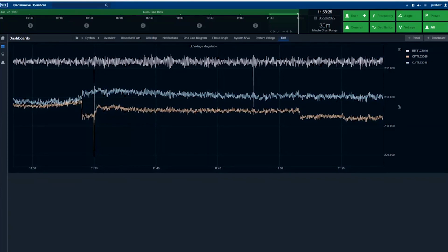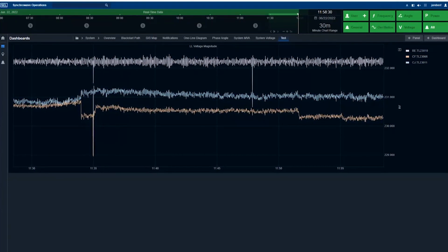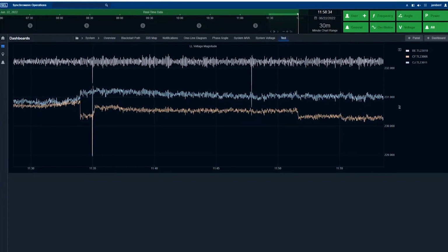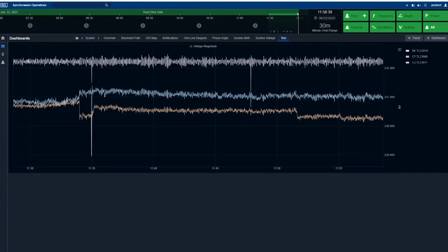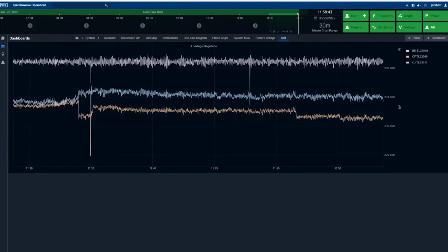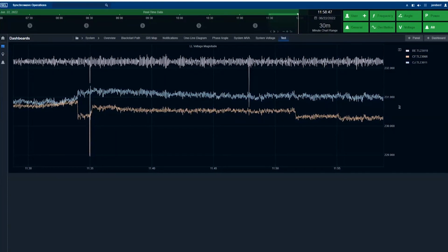Lastly, in terms of the basic requirements and locations, if you do have transmission lines that are high capacity lines that are critical, then I'd recommend installing, again, voltage and current measurements there. After that initial set, and again, the system can be deployed with just a couple of locations, and then you can work up.